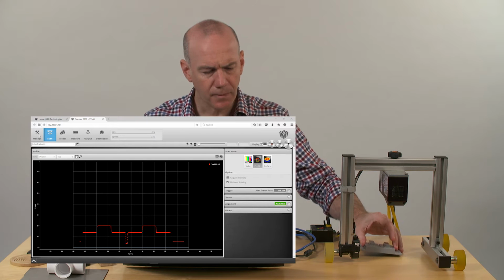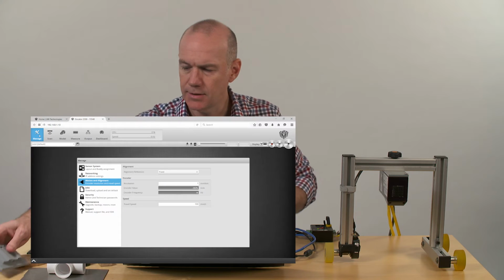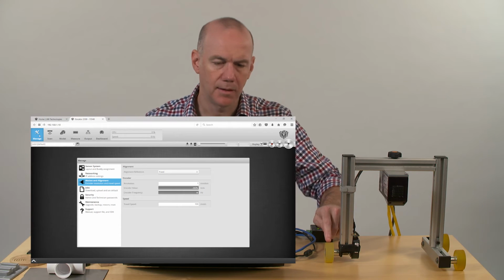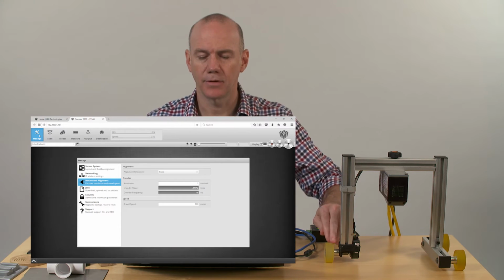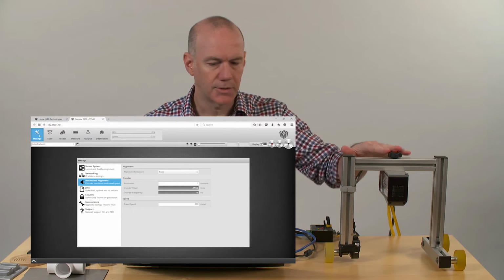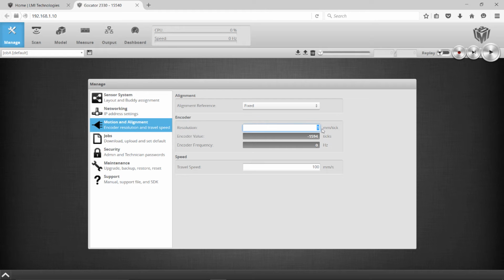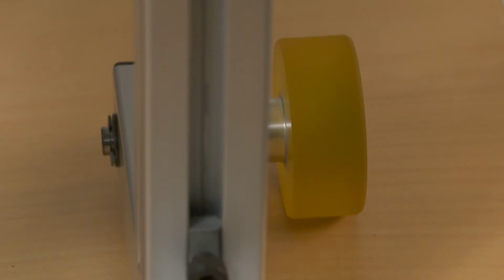So basically, what I'll do here first is I need to set the proper resolution for the encoder. I need to essentially calibrate that. And I just know that in this case, if I go into the manage screen here, this one in particular, the encoder and wheel is 31 microns per tick. That tells me when this encoder is ticking off motion, how far we've traveled,